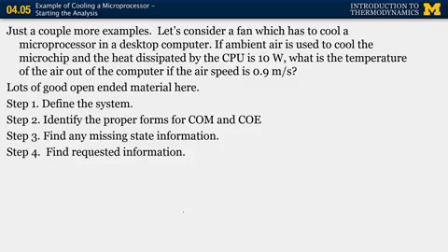And that's pretty consistent. The heat that's generated by those microprocessors can be anywhere from 1 to tens of watts of power. So what we want to know is if we have to cool that chip, we have to remove that 10 watts of heat transfer from the chip using air that's flowing over the CPU. What's going to be the temperature out of the computer if the airspeed into the system is 0.9 meters per second?